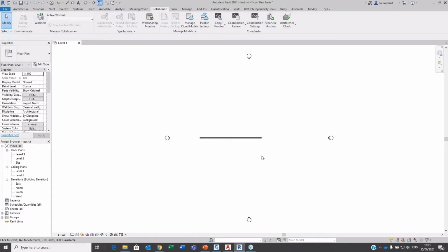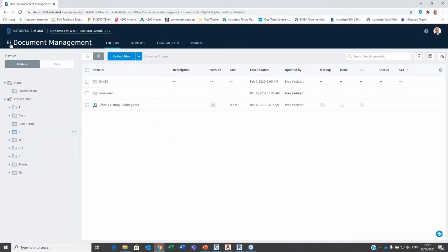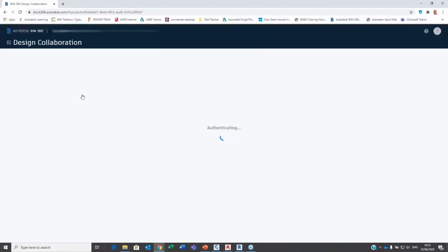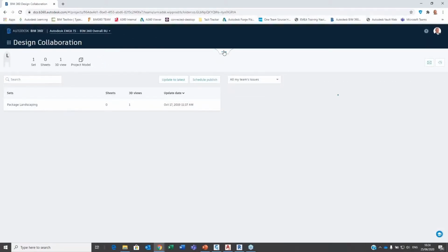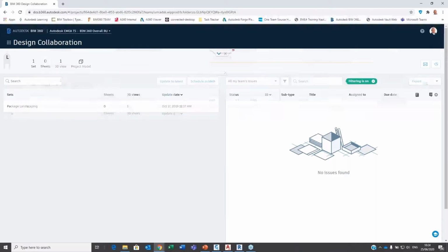So essentially what I've just done here without the worksets, that's BIM 360 Docs actually. That's a connection to BIM 360 Docs and having a Revit entitlement. When I go into BIM 360 Docs here and I swap over to design collaboration, that's that cloud module that I was talking about where we can look at the packages and communicating between disciplines. That's where you need a BIM 360 design entitlement as well. So if it's just the smaller company who's going to authorize you as the bigger company to say, yeah, you can take charge of the packages, the only thing they need is Revit, connection to the cloud, that's it, which essentially means BIM 360 Docs entitlement, okay?